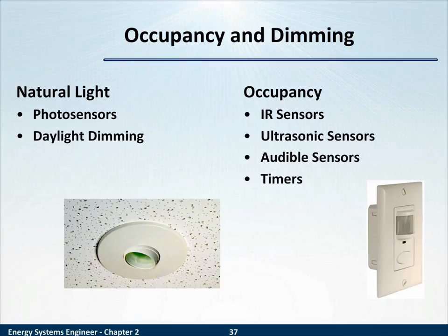One of the concerns and one of the things to be aware of is to make sure your control system is chosen well, because otherwise you can have a control system that's fighting itself. Natural light is going up, created light is going down, and those two battle themselves, and you can see this result in a flicker or a visible change in that lighting.